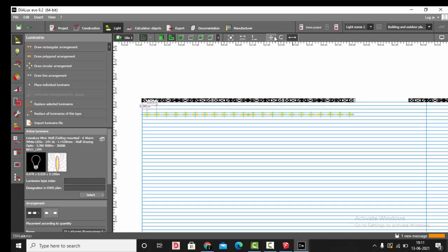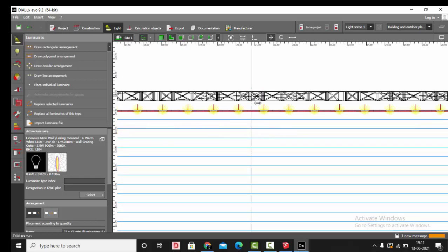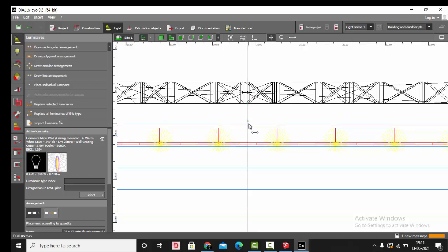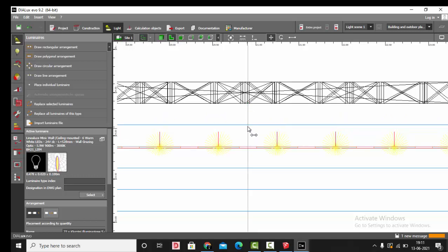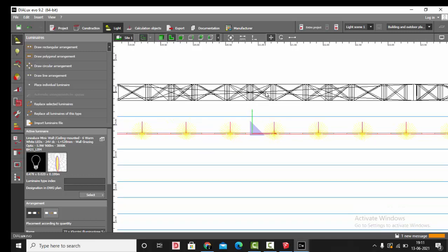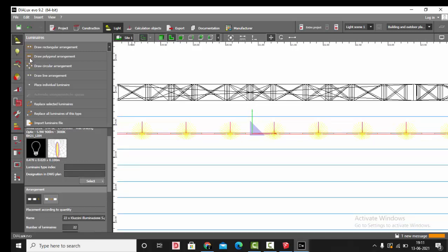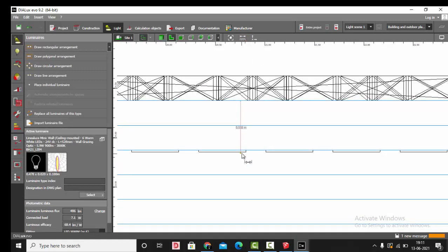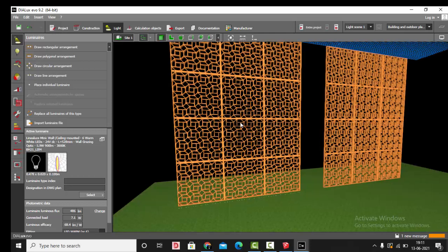We'll adjust the luminaire positions again. So this seems a bit too close for a wall grazing effect. It's only 200 mm, and let's try it with a little increase in the distance, maybe 0.4 from the object. So it's 0.5. I think that's cool.